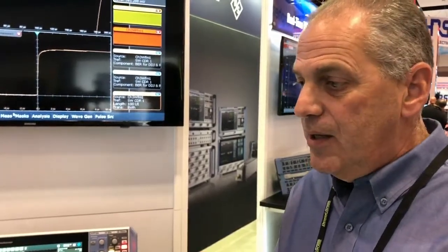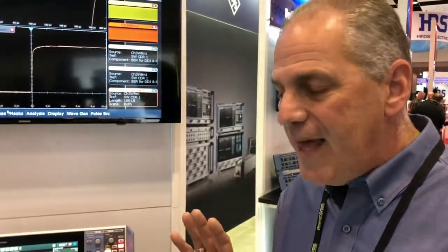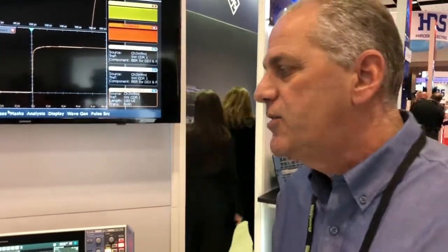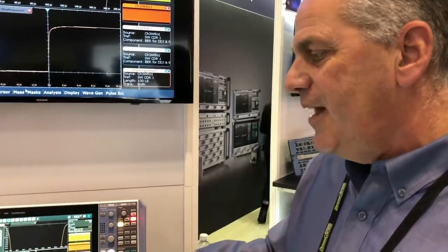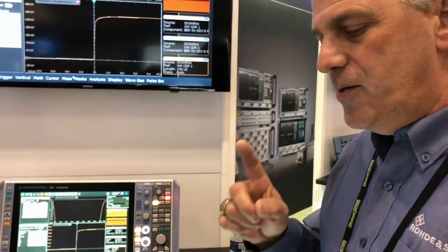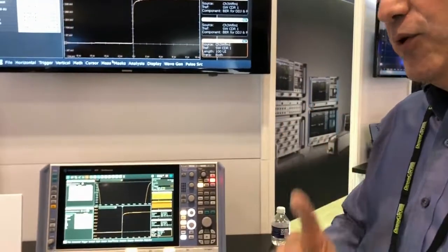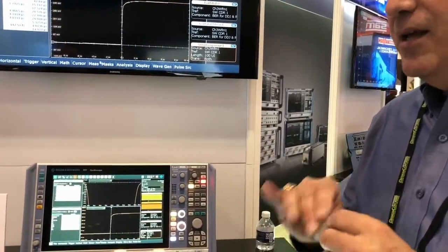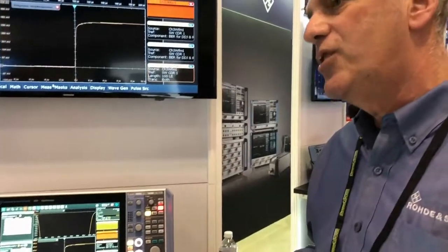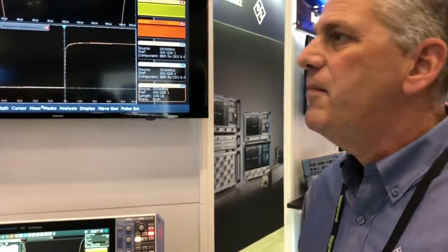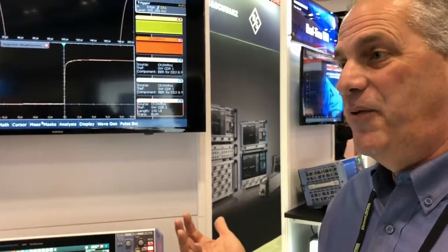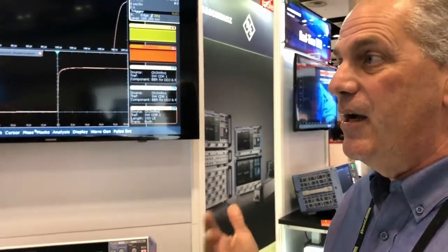Another form of jitter is something called periodic jitter, which is usually sinusoidal or repetitive movement of the edge in timing and also in amplitude. So what we do is we model, based on the data that we capture, the entire data record, the periodic components, both vertical and horizontal, and we model the step response. And then from there we get waveforms for each specific jitter type. We have a DDJ waveform, we have a PJ waveform vertical, and a PJ waveform horizontal, and then we have an RJ waveform. All those four waveforms make up our model.